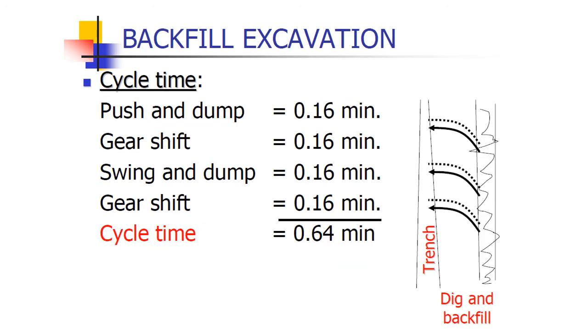It is the backfill excavation. However, there is one step difference here. You push and dump, you shift gear, you swing and dump, and then you shift gear again. This is mainly while dumping soil into a trench, or while backfilling a trench. Okay, so here the cycle time is 0.64 minutes, and we will continue in the next video, inshallah.